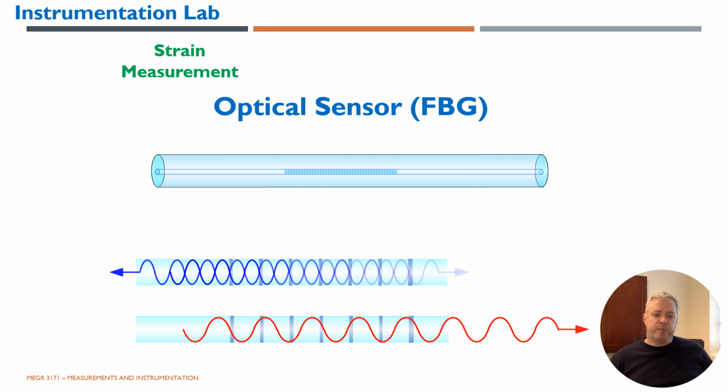So here is an example. You've got the Bragg sensor with the grooves close together, and you get this very tight signal. You stretch it out, you apply strain, and the distance between the fiber Bragg grooves is expanded, and you get this longer wavelength signal. So it's pretty obvious how it works, and it's simple, it's easy, and a lot of strain sensors now are this type of sensor versus the older strain gauge kind of sensors. This is just a better sensor.